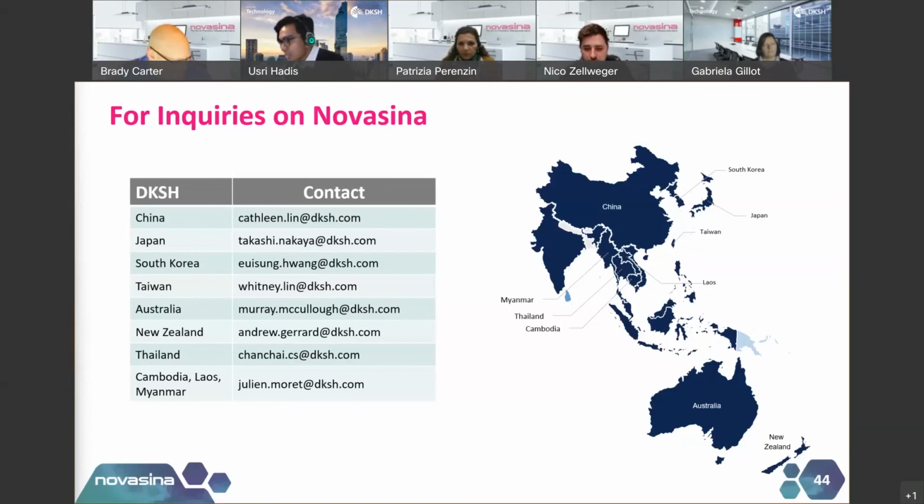Is the test result of water activity related to the relative humidity of the test environment? Yeah, it's a good question. As I stated, water activity and relative humidity are essentially the same thing. We just use the term equilibrium relative humidity. So it's the relative humidity measured in a container where you've achieved vapor equilibrium. The relative humidity of the room around where you're running the test will not influence what's happening inside of the instrument once you've shut the chamber and the test has started.